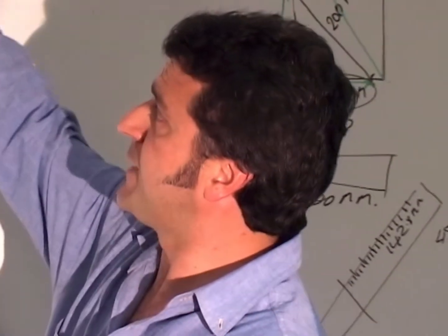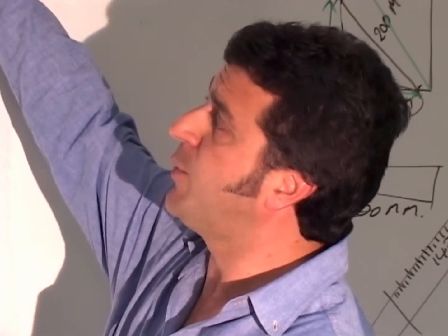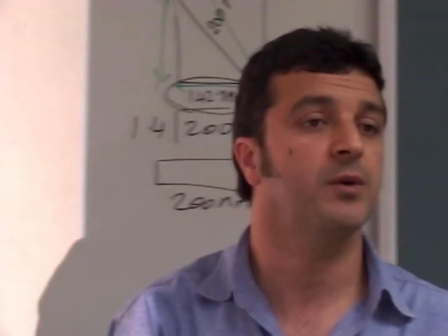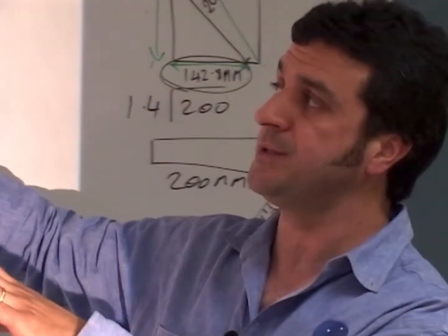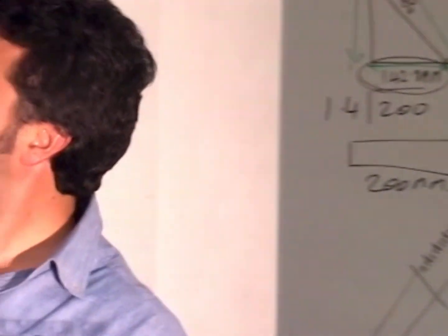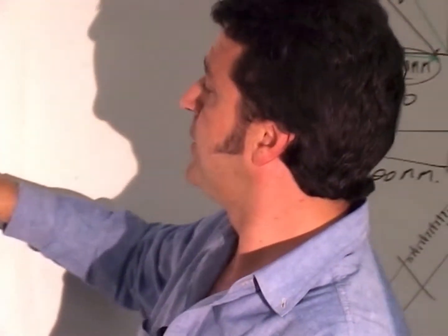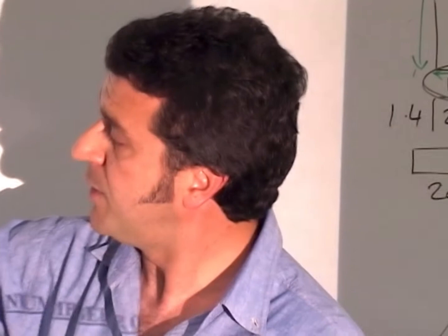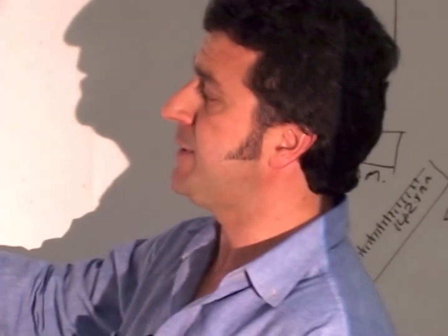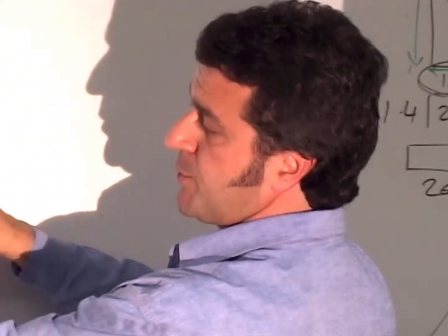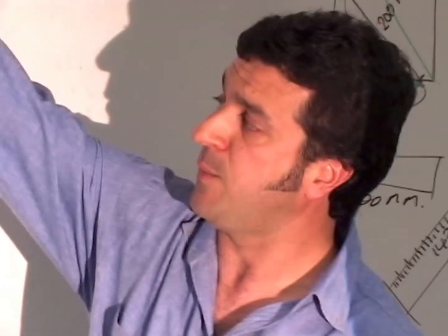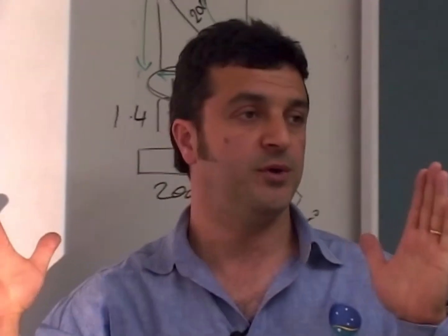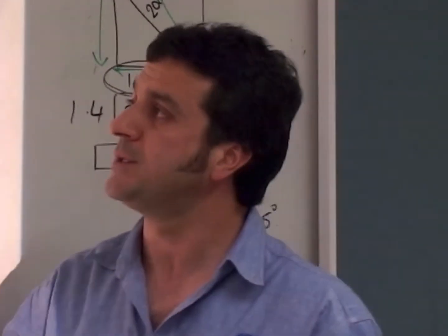Once we've got the tiles laid out on our little template, for which we're going to use cement sheeting or gyprock, whatever's available out in the workshop, as the building board to lay our tiles out on, we have to make sure we've got a perfectly square grid. If we're going to have 915 millimetres across with our spaces, which we'll check in the workshop, we need 915 that way, 915 that way, 915 that way. So it's got to be perfectly square and perfectly parallel to have a perfect set out.